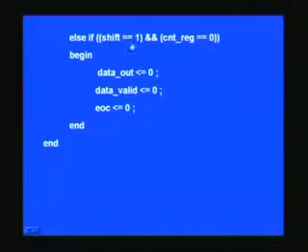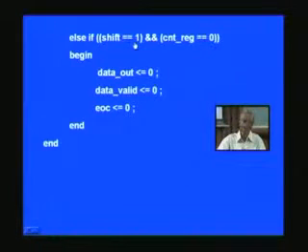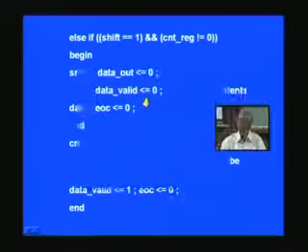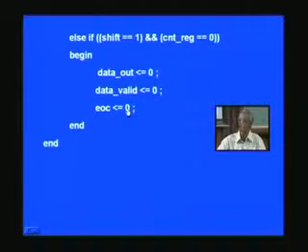Once again, if shift is still present and the counter value has touched 0, which implies that all the 16 bits have been already sent in the earlier block that we have seen, this will take effect only at the next clock pulse. So at the earlier clock pulse, all the 16 bits are already dispatched. What we have to do is please correct that. So end of conversion must be 1 here. So that's what is implied here.